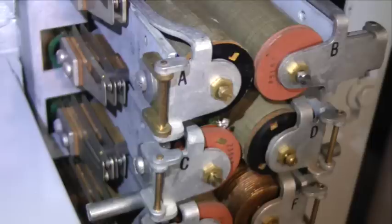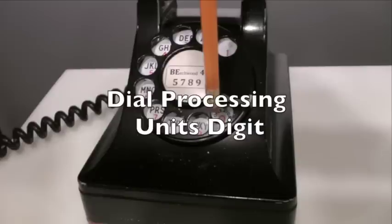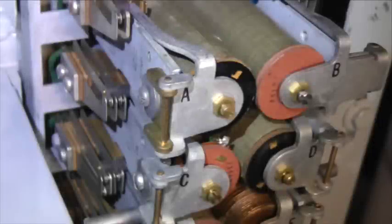Its release opens the energizing path for the vertical magnet and partially closes the operating path for the rotary magnet. At this point in time, only the A and B relays are operated and no further activity occurs in the connector during the interdigital interval. The caller now dials the units digit of the station number, which is also a 0. During the dial's wind-up, the loop remains closed and the A and B relays remain operated.